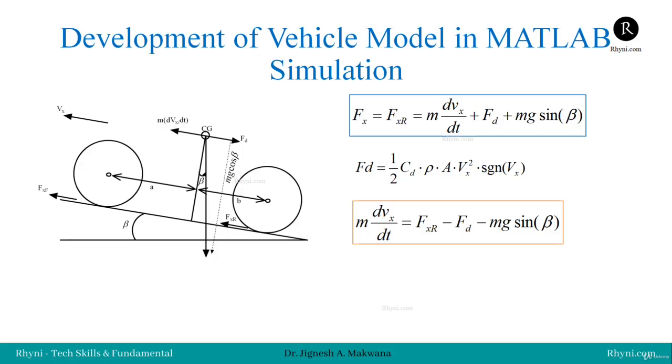So this is the system level simulation. Here our main input parameters are weight and inertia of the vehicle and supplied force. This is called system simulation because we generally use system simulation to represent mechanical, electrical or even magnetic or chemical systems. The next hierarchy in the simulation level is the unit level simulation, where we use in-depth simulation of different units like the motor, converter, engine or chassis, and then we join all these simulations together.